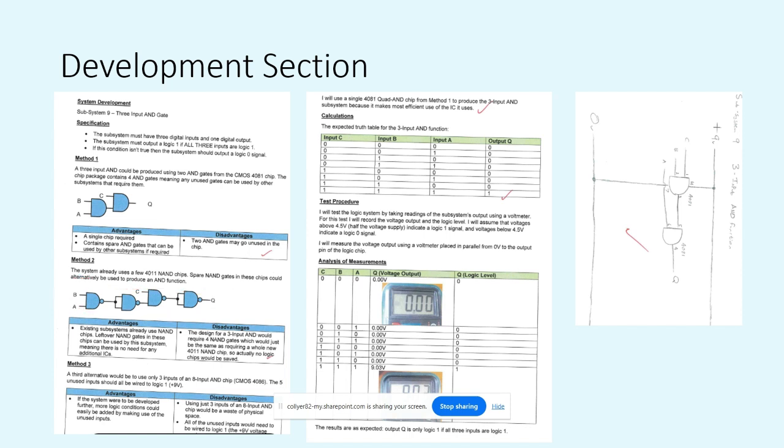So sometimes, particularly with logic systems, a student will say something like, this could be approximated with NAND gates instead. And they don't really make it clear how that could be done. So NAND gates are obviously a really good alternate to any kind of logic system because you can just do combinations of them. They do take up more space because there's more gates involved.